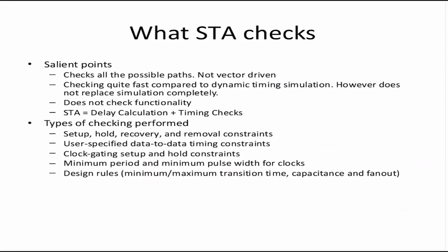So what does STA check? STA checks all possible paths. It's not vector driven. The simulation on the other hand is vector driven, in the sense that you give some values at inputs and you expect some values at the outputs, right? And you have to make sure that you cover all possible combinations. It is not the same with STA. STA is not vector driven. It checks all the possible timing paths in the design. Checking is quite fast compared to dynamic timing simulation, compared to the verification that you do with providing the stimulus.